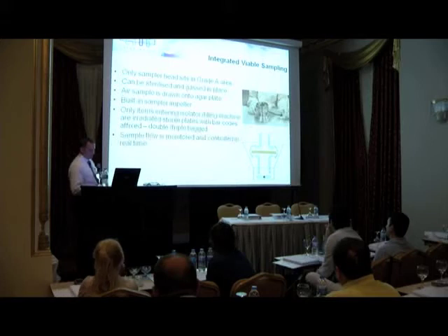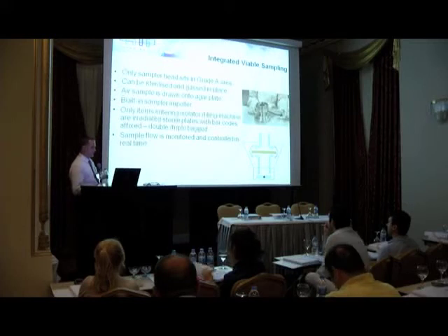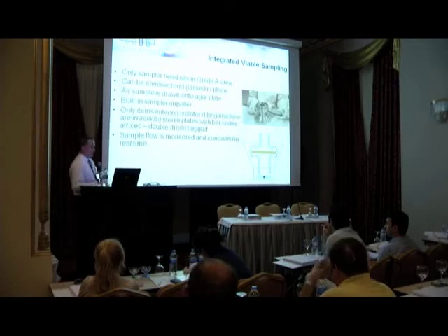And the critical thing that we do with these devices that other people don't necessarily is we monitor the sample flow. The standard says you have to monitor 1,000 litres of air. We see a lot of applications where an air sample is put in, and they say it monitors a certain flow rate. How do you prove it? You calibrate it once a year. But if you've got no reporting back, what happens when you come to a year and that flow rate is found to be wrong? When did that flow rate go wrong?